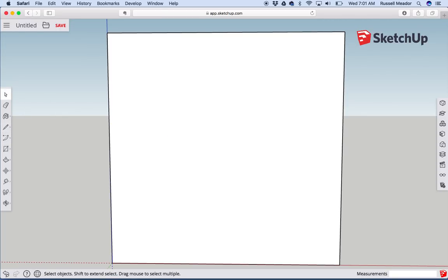Quick idea of what I just did, or if you need to use an arc for something, it's really easy. You're just going to come to the point that you are. It's showing me the length. Let's say I want to bring it out 3 feet. If you look in the bottom right, you'll see my 3 feet. It's going to take that along that edge. It's at 3 feet, and when I click,